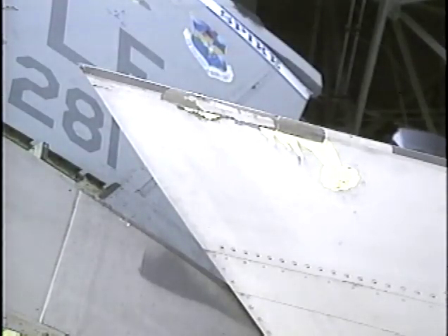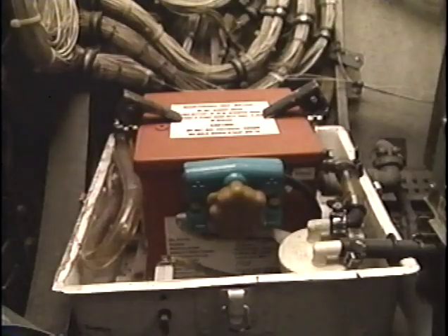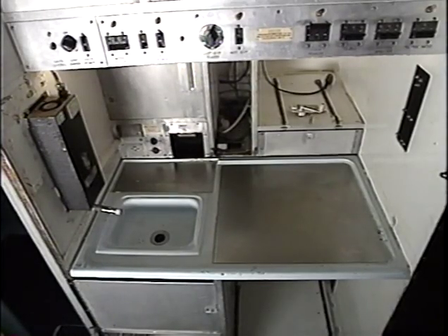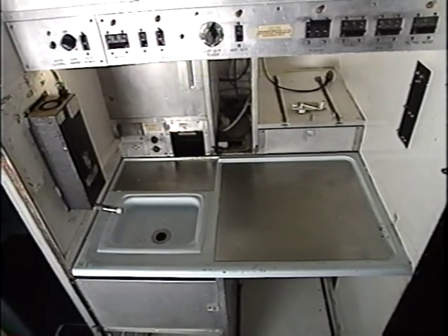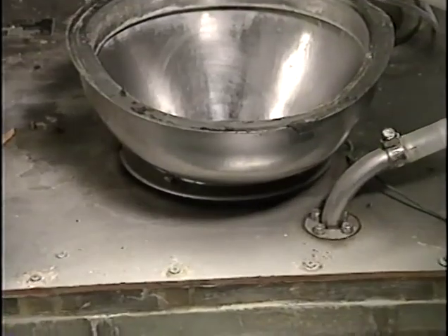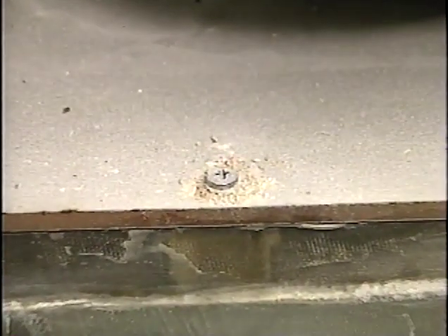Engine inlet and aircraft frontal areas, such as leading edge surfaces, are constantly undermined by rain, dirt, dust, and other abrasive elements. Battery compartments offer a unique problem on the aircraft, despite the special paint coatings in these areas. Leakage of electrolytes from the battery cases or fumes from an overheated battery can cause rapid corrosion. Galleys, lavatories, and crew relief areas are extremely corrosive areas because of food spillage and urine spray. The latrine and crew areas should be inspected and cleaned after each flight.